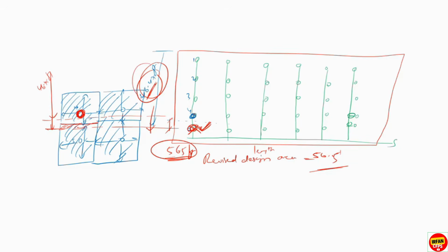In uniform sprinkler spacing, you are using 46.47, but if you have non-uniform sprinkler spacing, you need to use 46.47, but if the distance enters into the fifth sprinkler coverage area, as I showed you before, then you need to consider the fifth sprinkler, otherwise consider up to 4 sprinklers.